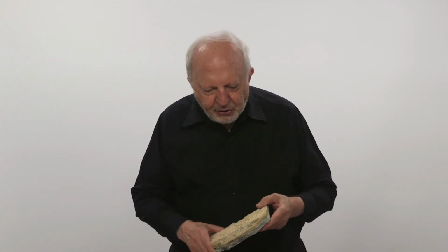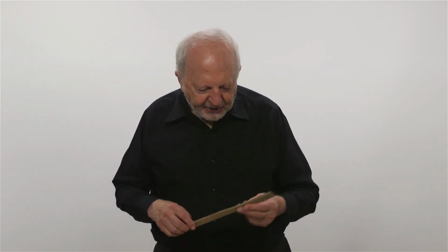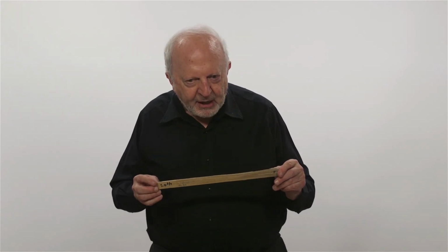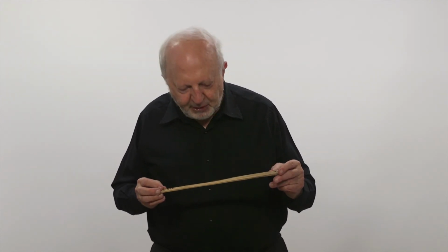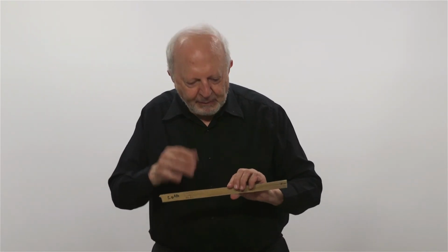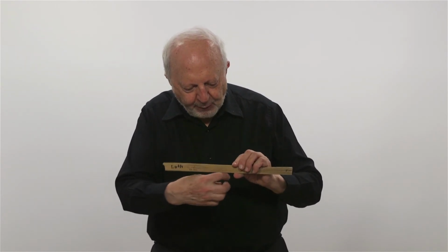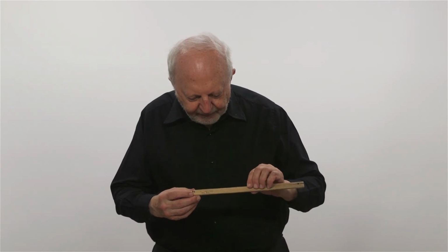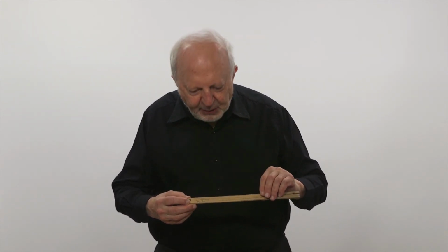Now from there we should turn to the internal plastering finishes. Commonly inside, plaster would be plastered over laths, not lathes, but laths. These are ideally split timber. Split timber is better than sawn timber because it has a better bond to the plaster, but sawn timber was sometimes used. So these are placed over the whole framework in the wall with smaller gaps between. The plaster is plastered over and it forces its way into the grooves between and therefore holds onto the wall. And that's the standard way of plastering right into the 20th century.